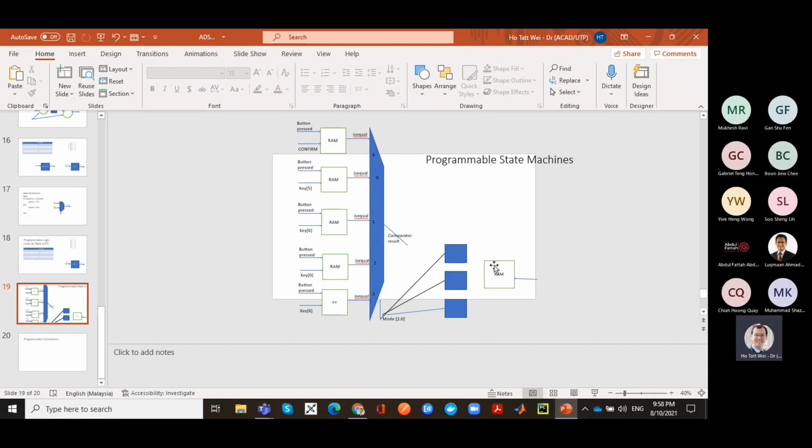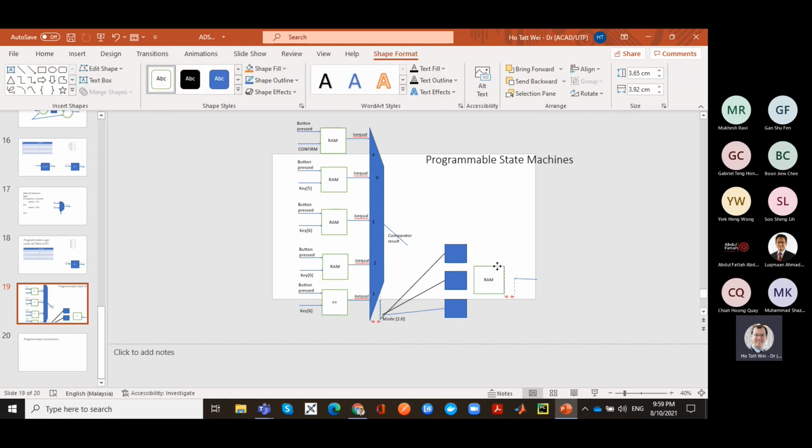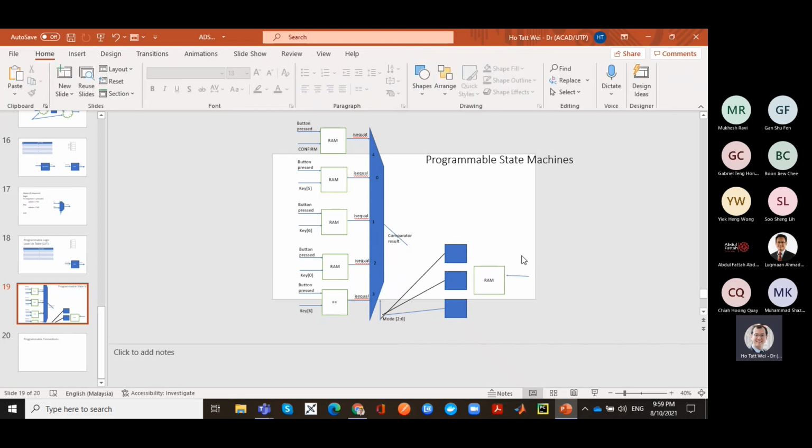Guess what? Each machine instruction is basically stating the next state, and the next state is actually selecting the mode of operation. So a processor is nothing else but a flexible state machine whereby you code the next state in an instruction memory, and that instruction memory is implementing a lookup table that is selecting which mode to operate, right? Which mode. Okay, so what do I mean by mode? Well, that's your instruction.